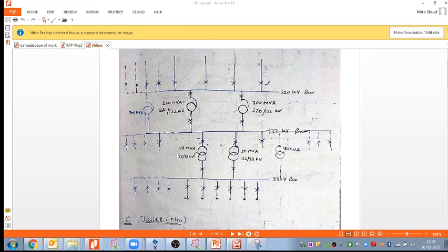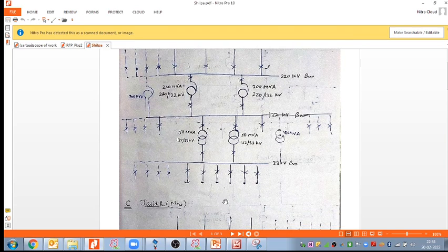So I'll tell you what is best here. Please do not indicate this 132 kV feeder here. Please take this one here, because there will be a double circuit line, so both transmission lines will go from the same tower. So both line bays should be together. So please take this line bay here. Okay, you understood the observations now. Then two ICTs, 80 MVA ICTs. Then 33 kV, and this is all fine. Your SLD is good. That is the one observation.